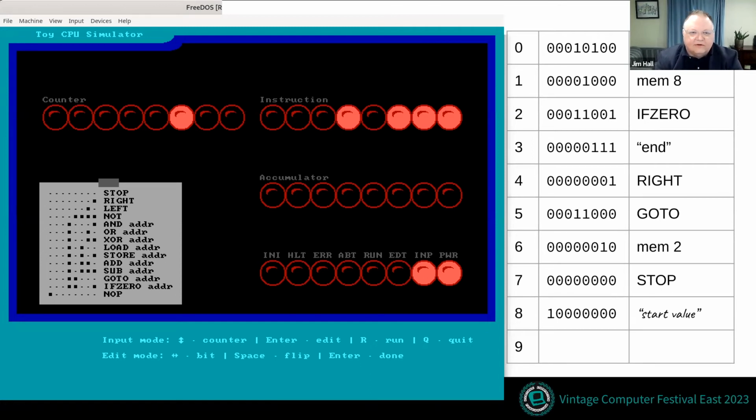And then counter 4, we need to do a write instruction. And so again, I kind of picked the right and left shift instructions by making it look like a right and a left. And so the right is just the bit on the very end, the 1 bit. And then the left shift would look like this. It's the bit to the left of that one. I could have used a bit that looked like this to do a left shift, but I wanted to have the instructions go in more or less numerical order, so that having a left shift and then a right shift.